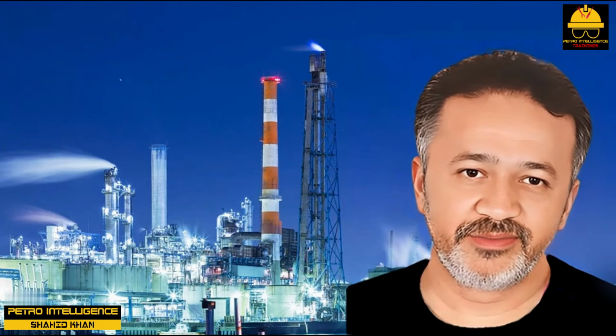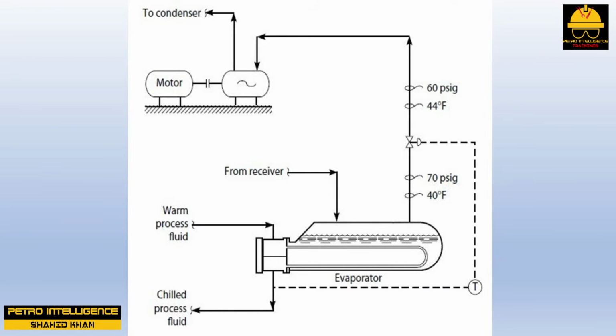Compressor operation. Let's say we have a centrifugal refrigeration compressor driven by a motor. The motor is tripping off because of high amperage. Should we open or close the suction throttle valve shown in the picture? Answer is close it. Of course, both the evaporator vapor outlet temperature and the process fluid outlet temperature will increase. But that is the price we pay for having too small a motor driver on the compressor. Does this mean that when our home air conditioner gets low on Freon, our electric bill drops?